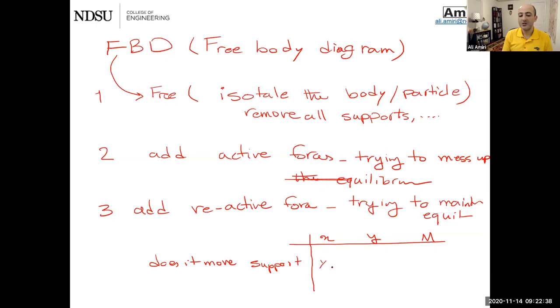It's either yes or no. Does it move in Y? It's either yes or no. Can it rotate? It's either yes or no. And wherever you see a no, that's where you are supposed to put a force or a moment in that direction. So this is to figure out the reactive forces.